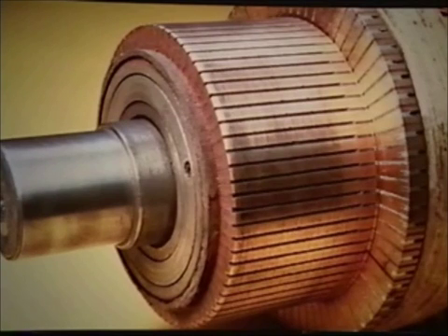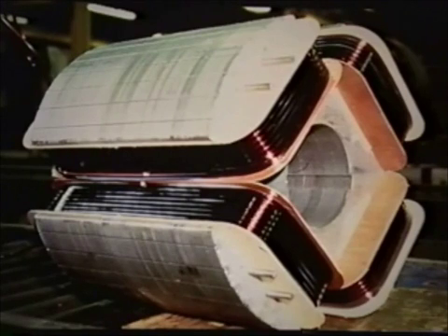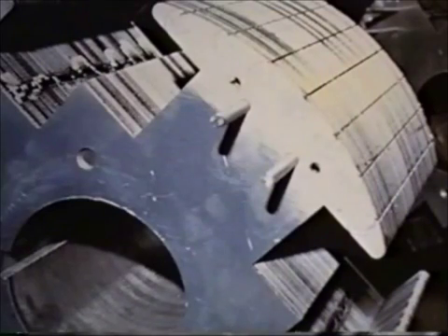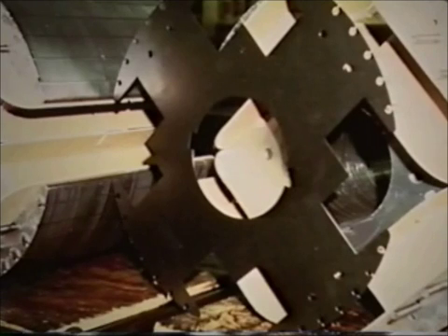A commutator is a device mounted on the shaft of a brush-type exciter that mechanically rectifies the alternating current generated in the exciter armature to DC. A commutator is simply a mechanical rectifier. A coil, or coils, wound around the field poles of an alternator through which the DC excitation current flows, creating a magnetic field, are field coils. The field pole is the part of the magnetic structure of an alternator on which the field coils are wound.